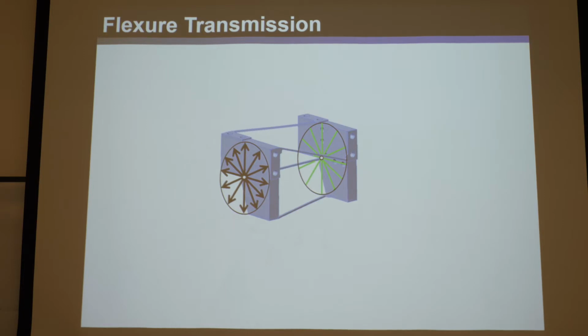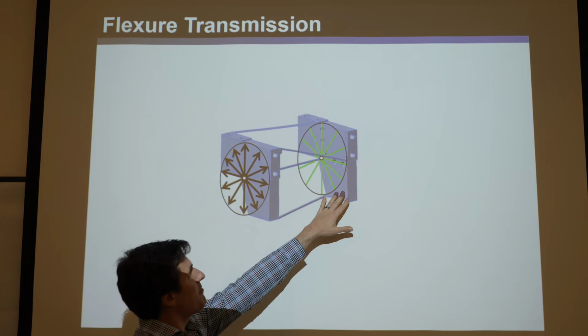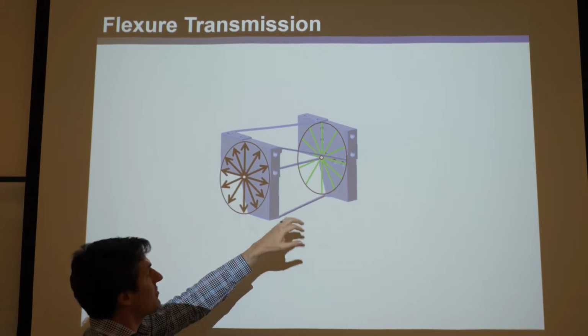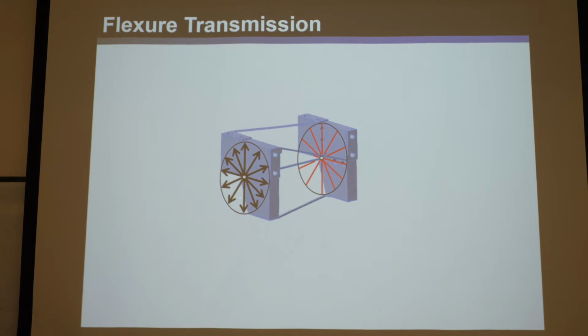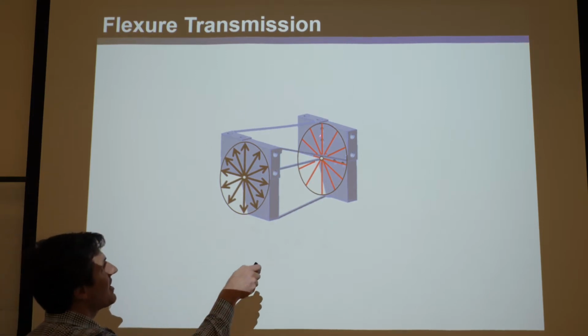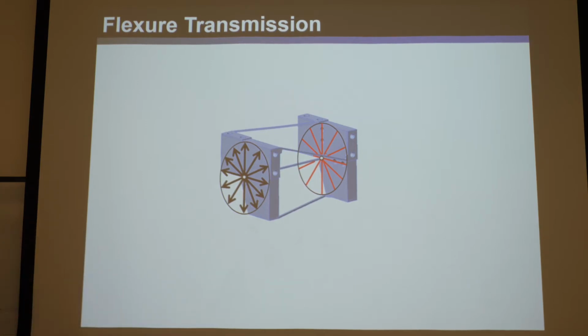So we're going to add a bearing onto that only allows translation there. Then we're going to add a bearing on that, some kind of flexure bearings that force these to only rotate around those. So that every time you translate one of these, this one's going to rotate with that transmission. If you translate one of these, the parallel one's going to rotate with that transmission. Okay? And P will be our approximate transmission ratio. Okay, or at least get us in the ballpark, and then we can tune it later.